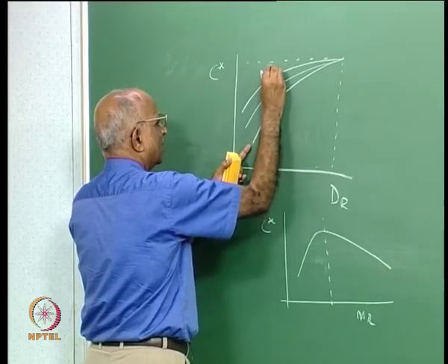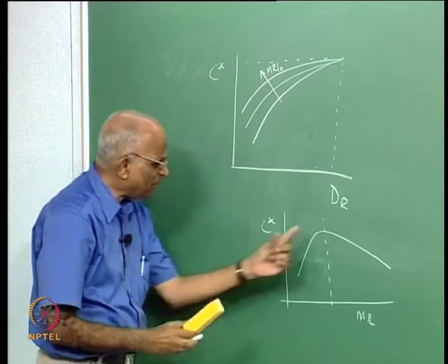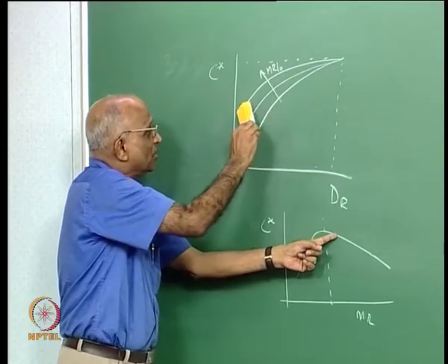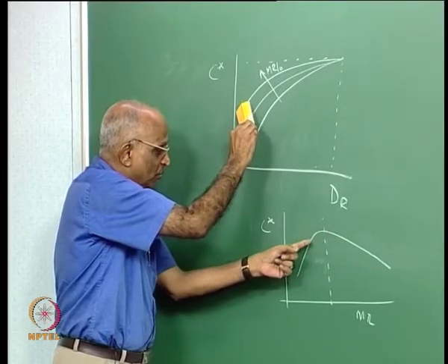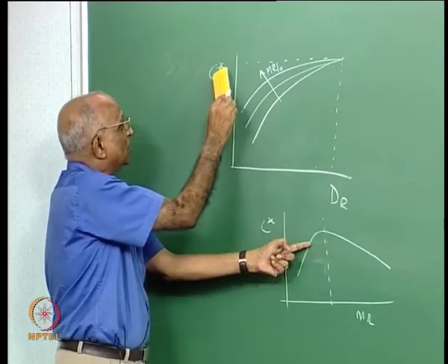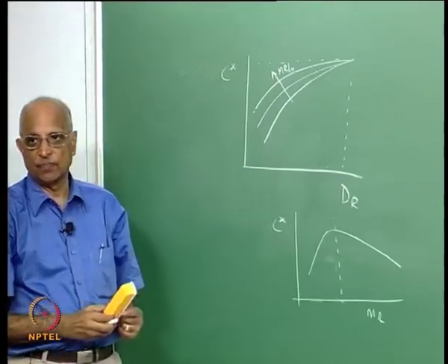This we say as a function of mixture ratio nominal. All what I am saying is, if I were to have the nominal here, then the change in c star is a little bit less, whereas if I choose a value here, I am in this gradient and therefore it will fall, and this is how c star varies with distribution parameter and with mixture ratios.